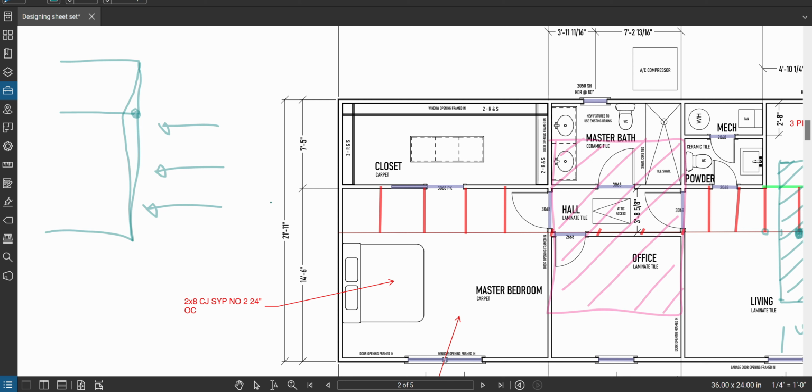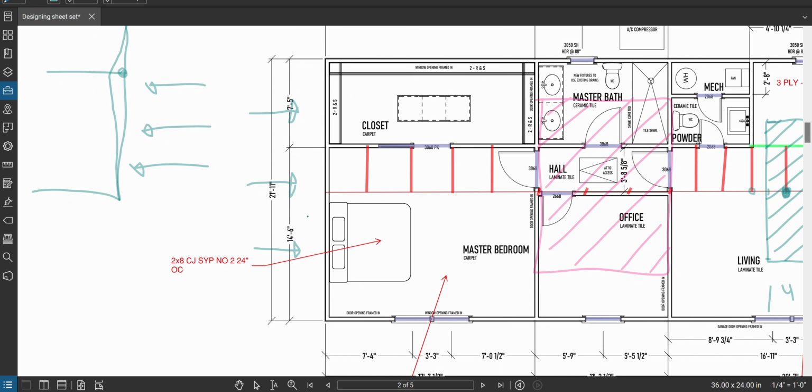So what we're doing is we're looking at this whole wall that's being blown by the wind, and the same thing applies with suction. Suction happens too, and the wall can be pulled outward. So when the wind blows on this, I have support on this wall, by this wall, and by this wall. I don't have support here in the middle. What I want to do is try to support this thing every 6 feet, right?